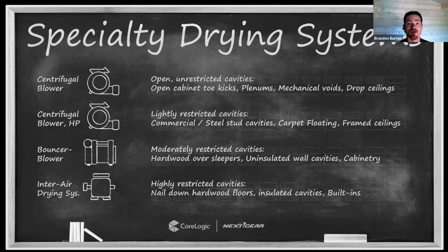The 1 horsepower air mover is a great drying system if you can remove the vinyl cove, put some 1-inch holes behind the vinyl cove, and then use the boot system on these, which is just a vent system you can attach right up to the wall. You could put one of these boots off of this air mover.